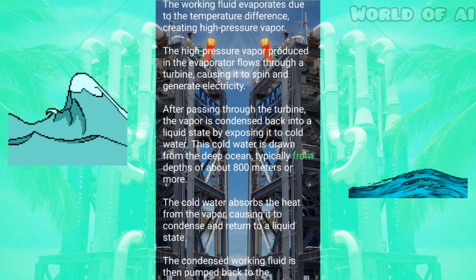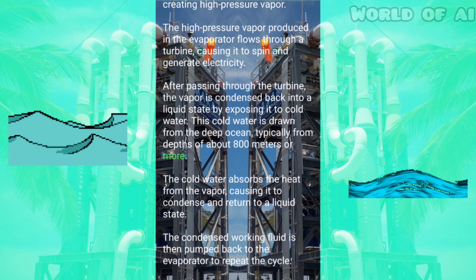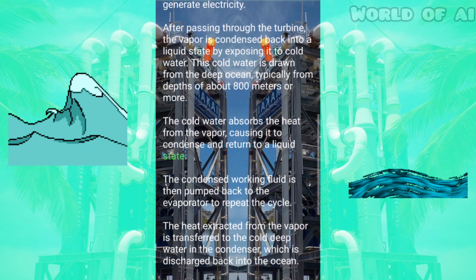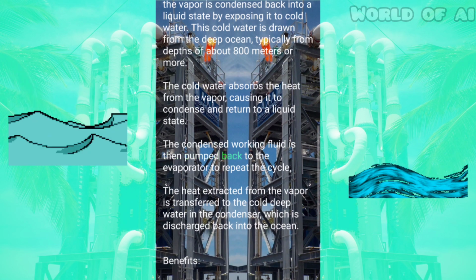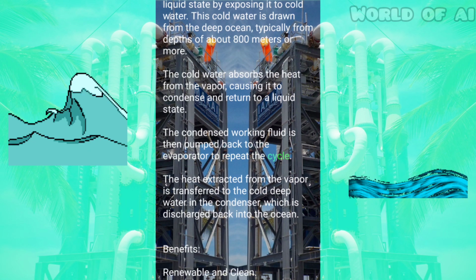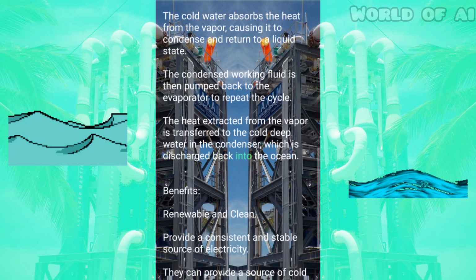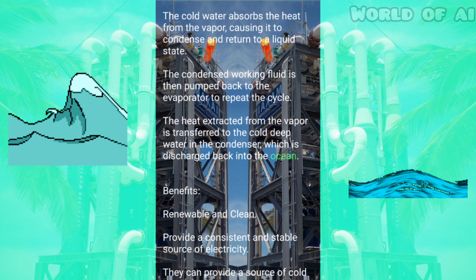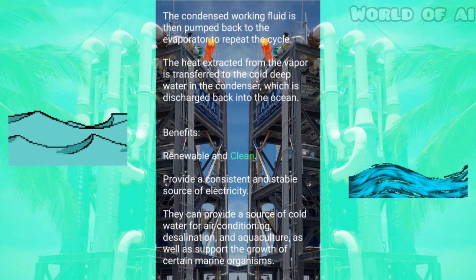This cold water is drawn from the deep ocean, typically from depths of about 800 meters or more. The cold water absorbs the heat from the vapor, causing it to condense and return to a liquid state. The condensed working fluid is then pumped back to the evaporator to repeat the cycle. The heat extracted from the vapor is transferred to the cold deep water in the condenser, which is discharged back into the ocean. Benefits. Renewable and clean.